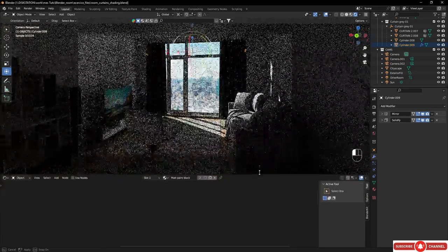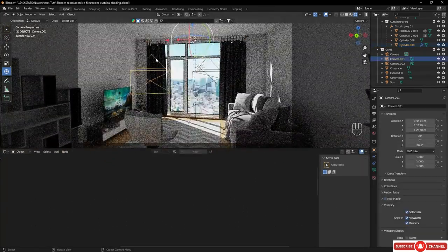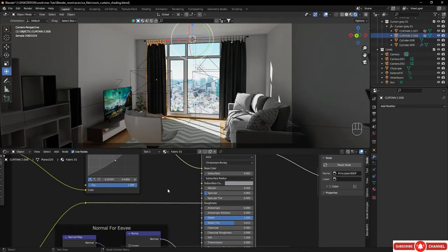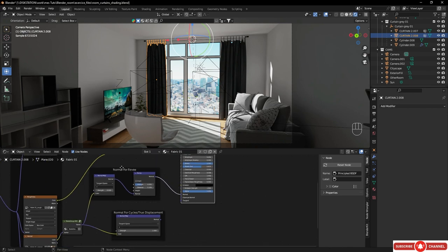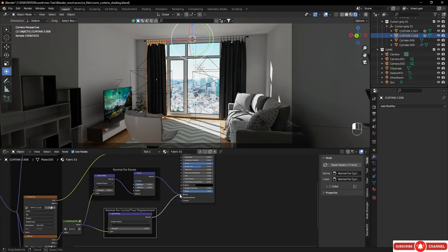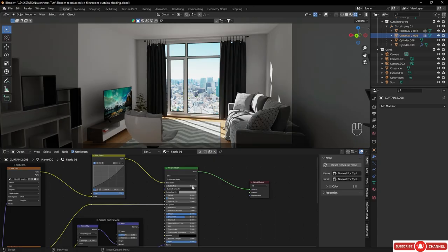We're going to enlarge here and take the shader of our curtain. And we can take a look, and it looks like this. Okay, so first, because we're still using Cycles, I'm going to switch here and plug the normal here. We'll have the right behavior. But still, it's not the problem here. I'm going to also hide the overlay. The problem is we need to use the subsurface. Subsurface is going to let the light through it. It's going to travel inside and look much better.